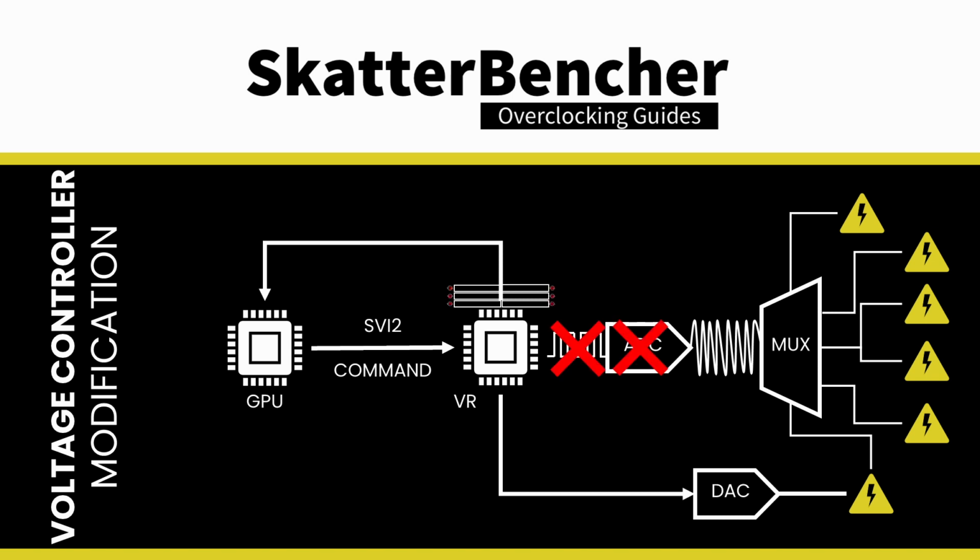By disabling the ADC, we essentially force the voltage controller to stop updating those registers. In fact, the information available in those registers would be the last updated ones. If we disable ADC when the GPU is in idle, those values will be very low. Again, we don't know how the SMU interacts with the voltage controller, but as a practical result of disabling ADC, we can use a lot more power.